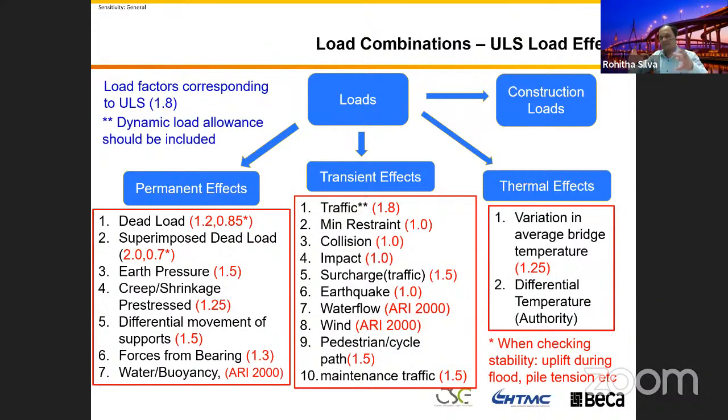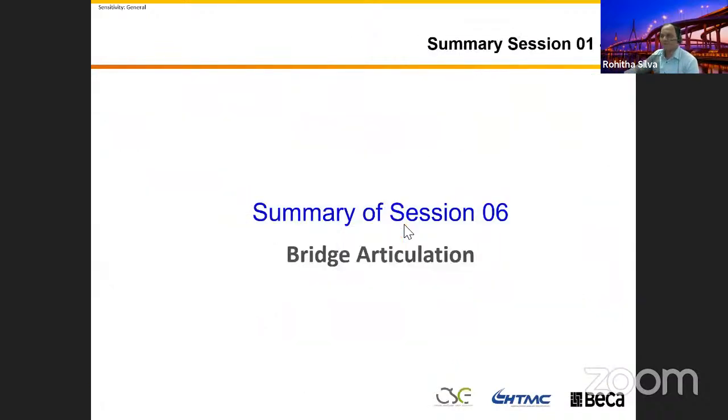If there's an earthquake and uplift from the structure, that's going to govern the design. So you have to look at this in your design, especially when you check your pile for tension; you need to use this load combination. So I explained this in detail. This information is quite important when you're going to do bridge modeling. But for today's assignment, we're not going to go to that extent, because if I were to go to that extent, I would need to spend at least 7 to 8 hours with you.